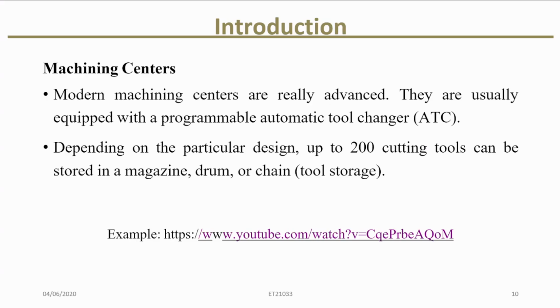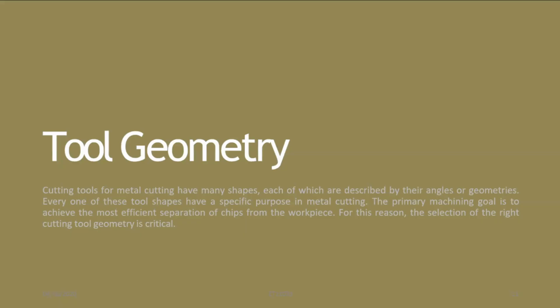When we consider the classic transfer line versus machining center, in high volume transfer lines, each station does one OP. In a machining center, we bring multiple OPs to the client work. So in one setup, you can use many tools, which puts pressure on choosing the right insert geometry for each OP. Then we can move on to the tool geometry.